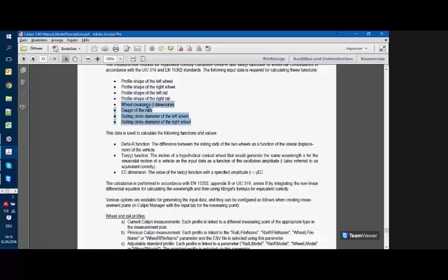For the others, you need just to have the value. You need to have a value of the wheel clearance, and there also you can use the measured value of the back-to-back distance within your measurement plan. The gauge of the rails need to be defined as a value because we cannot measure it currently. We do not have the rail geometry model available, but there are some plans to re-implement it again. And finally, for the rolling circle diameter, you have also the possibility to use the directly measured values of your actual wheel set during the measurement of it. So that's the first option.